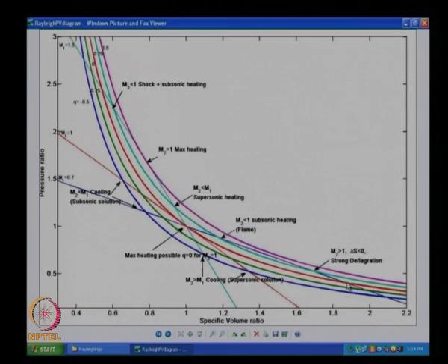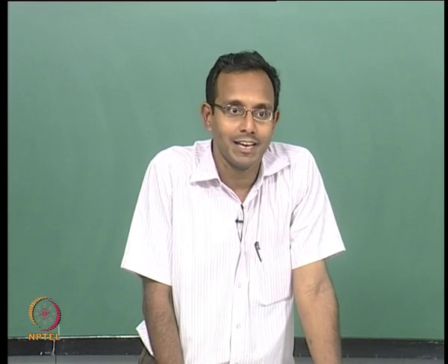This corresponds to what we saw in our original BZT flows. We said somewhere that we have a strong sudden expansion wave, as in an expansion shock. It becomes an expansion shock if I think about that particular case. And in our flow, where P equals rho RT is our gas law, it is not going to be valid. For us, our delta S will be negative.